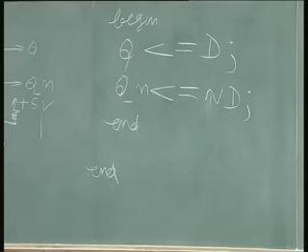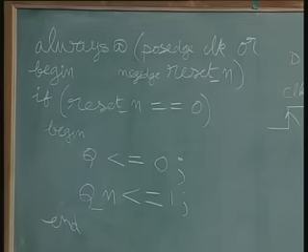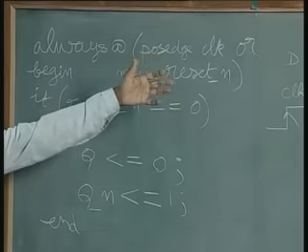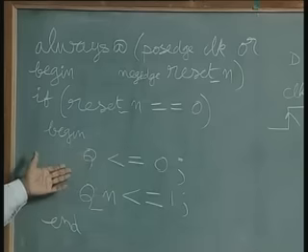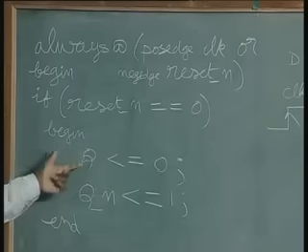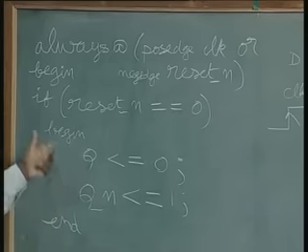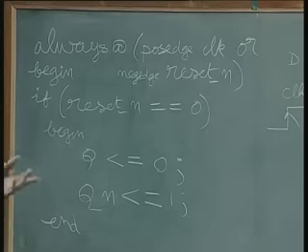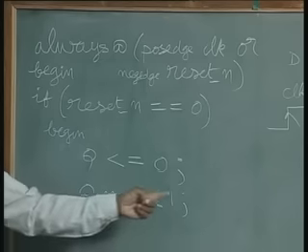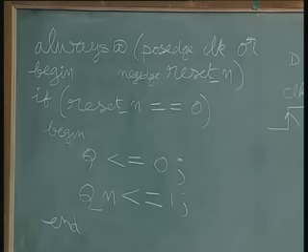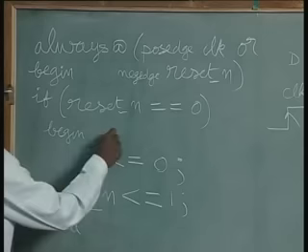So this completes the flip flop. You would notice that it is almost one to one correspondence with what a flip flop does. First you do the resetting, only thing is you have to take the trouble of writing two statements here, and in fact you can avoid this also and take care of it in some other logic which you are going to do later on based on this. So you can even dispense with this, in which case begin and end can also be dispensed with. Now, I would like to point out one more thing. You have had a new symbol here.